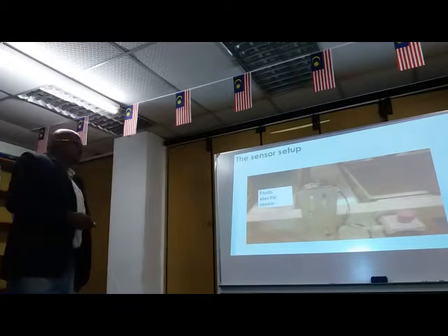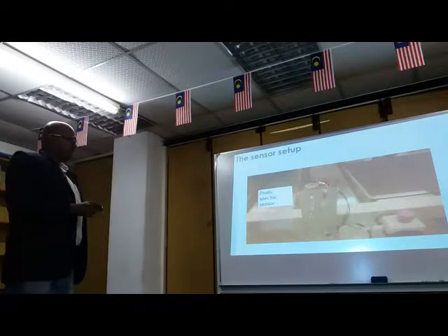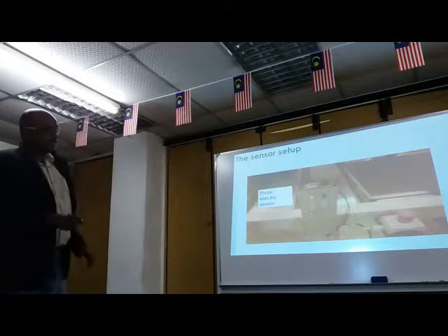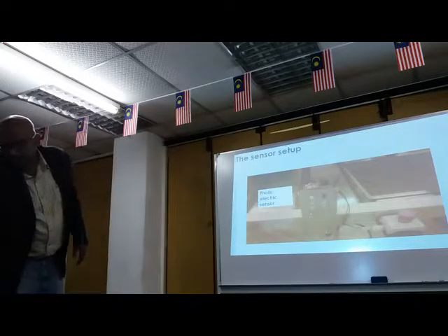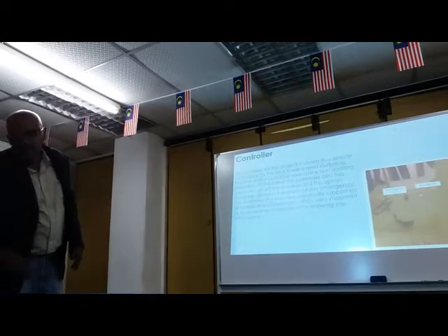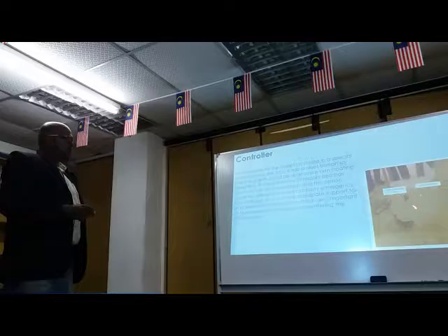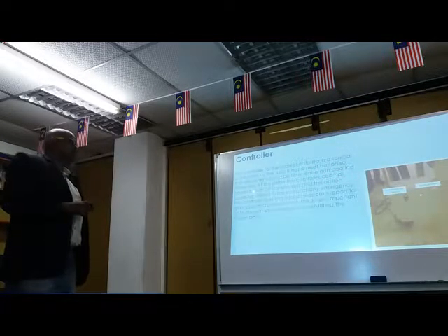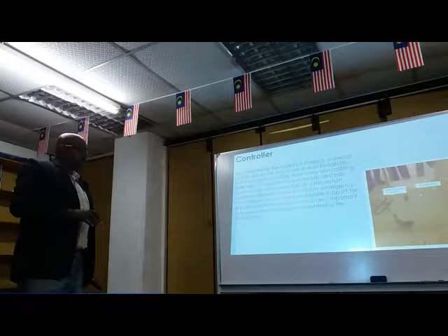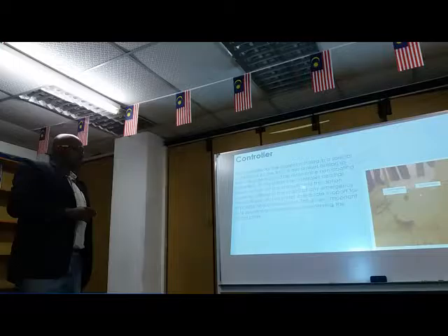So this is how we set up the sensor. We have the photoelectric sensor here. This is the picture from the actual implemented area. And we also have the controller. The controller for this project is stored in a special control box by the tool. It has a reset button so that the system can be reset once a non-coating is detected. So once we recover the situation, we can reset the condition. At the same time, the controller also has the option to turn off the breaker, and this option could be utilized in the event of any emergency.